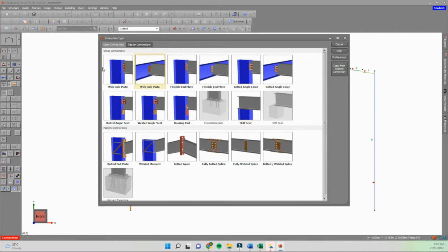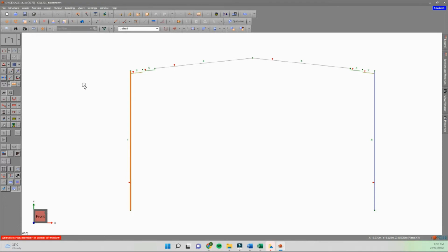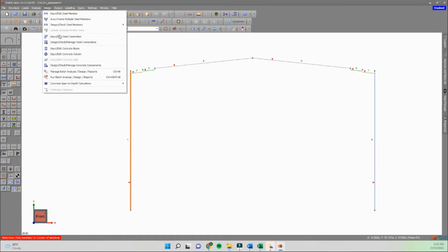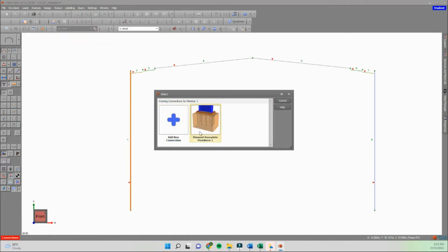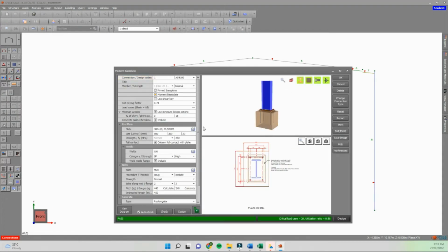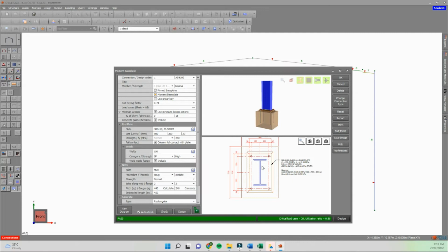This is a strong commonly used connection within the warehouse industry, being very cost effective in comparison to other connections of similar strength. The column to concrete plinth connection is responsible for holding the frame in place. However, the holding down bolts with the base plate also prevent any lateral movement in the structure. Once the footing is poured, the timbers and the holding down bolts are stripped and the columns are bolted to this connection. However, in this instance, for the purpose of simplicity, we have chosen to consider the columns as being bolted onto the ground slab rather than the footings.